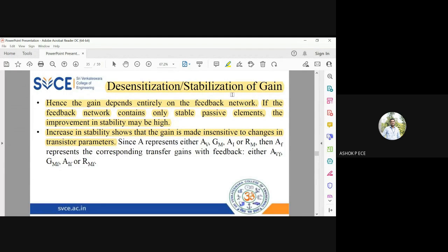So if you change the amplifier bias resistors, the power supply given to the amplifier, the transistor H parameters, or add a new transistor, whatever you do, the gain after feedback is going to be essentially independent of all these changes, and it is going to be completely stable.